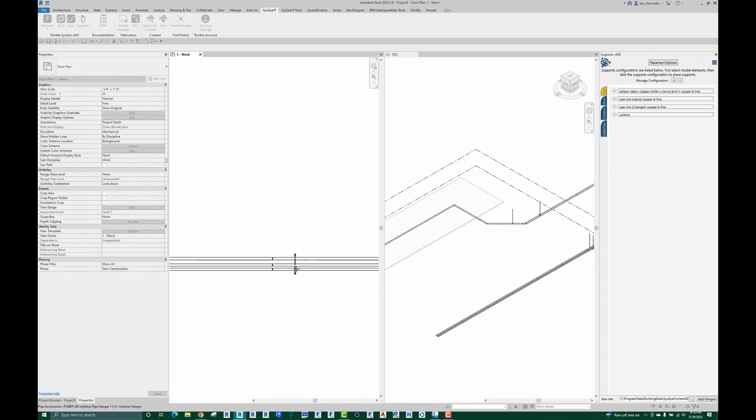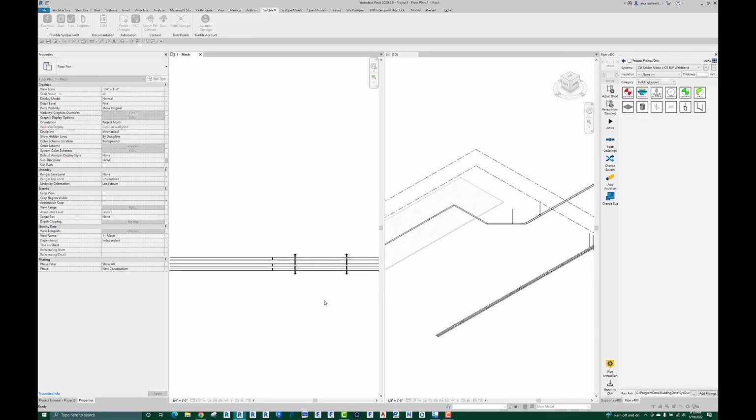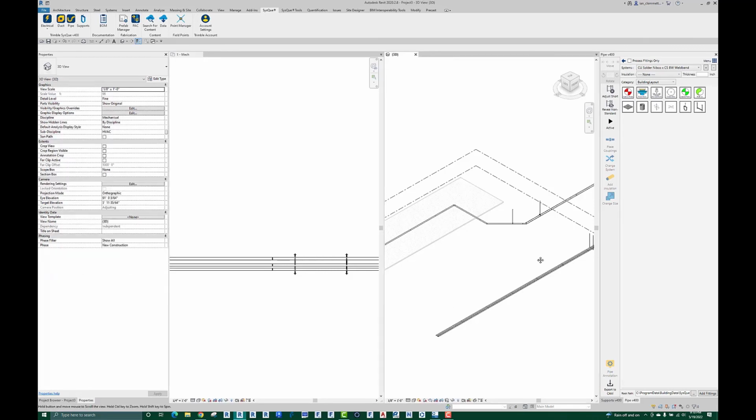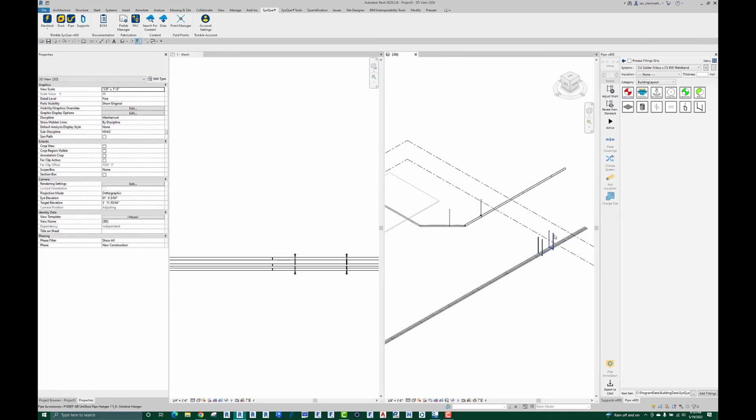And you can see, it places it, then organizes it and stretches it to make it fit. I could pick this pipe. And essentially the same thing happens. Places the hangers on there. And repeat as necessary. Right-click cancel to actually finish the operation. And again, because there is no structure here, these are basically just extended as they are. So that's basically the manual placement of hangers.